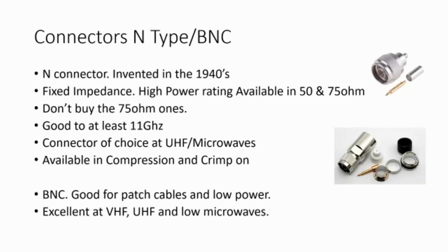Just getting some samples to show you here of N types. I've got a couple of them here if they all fit in the picture. So yeah, watch out for 75 ohms. If you see cheap N plugs or BNCs, make sure they're 50 ohm before you buy them. They're good to at least 11 gigahertz, so they work well into microwaves. They're the connector of choice for UHF and microwaves, and they're available in a compression or a crimp-on. I've used both. Both work very well.